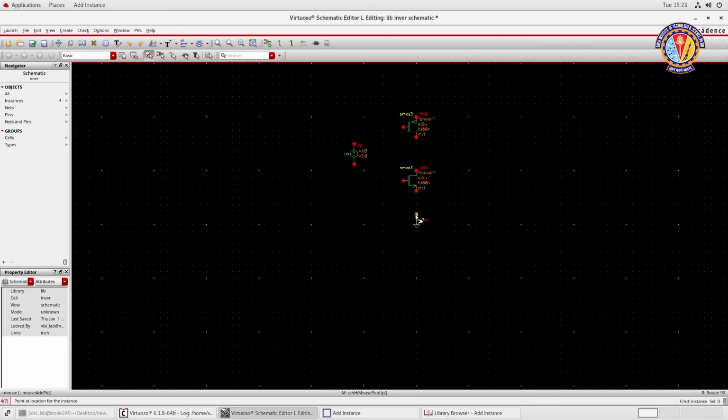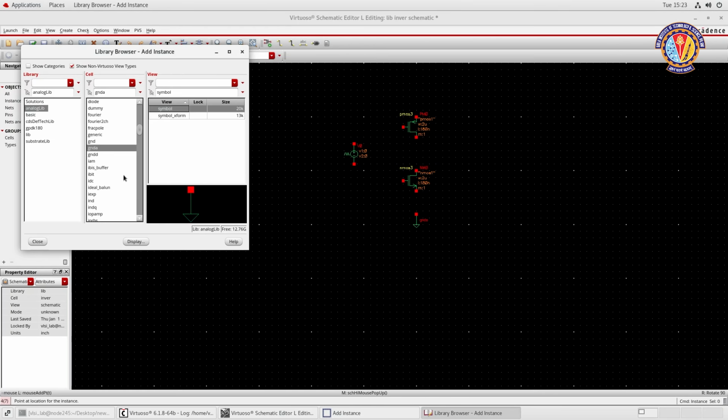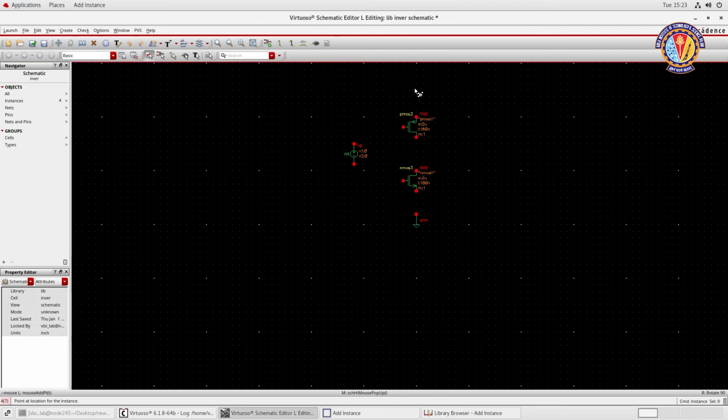You will have your ground. But there is one additional component which we need to add. So you may follow the same practice for all the circuits hereafter, because hereafter it will be combinational, sequential. For any circuit, you will have something called VDD, the common power supply, right? So how we can create VDD is, you again have a source called VDD. So you place this VDD because the VDD will be connected to the source of the PMOS transistor, right?